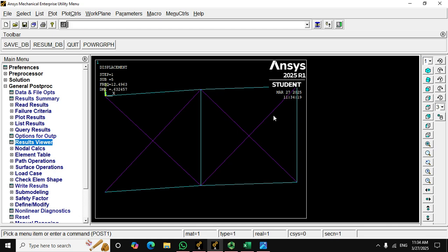And then in 3D, those 4 points have a total of 12 degrees of freedom. So we should be able to find 12 natural frequencies and 12 mode shapes, and we saw all of them.